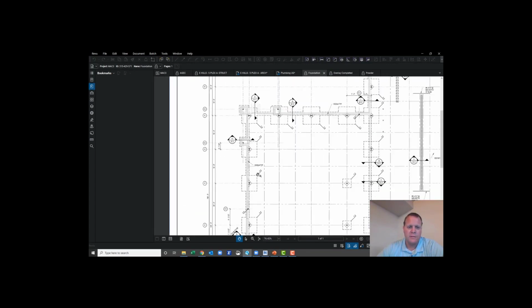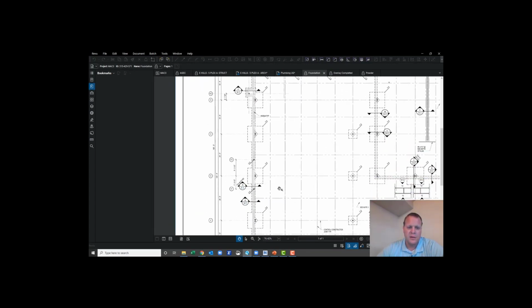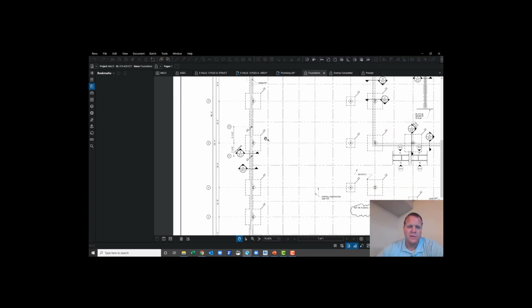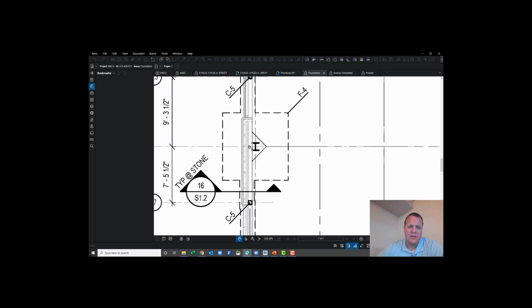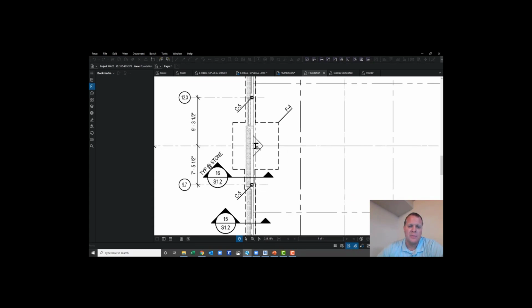And we see 14, all of them have the foundation F4 spot footings. All of them have an H column, the I-beam column. And so we've got roof drains coming down, at least one of them is taking up space, is going to be in conflict with the space of this footing, and maybe even the fur out in this location, right? The framing.